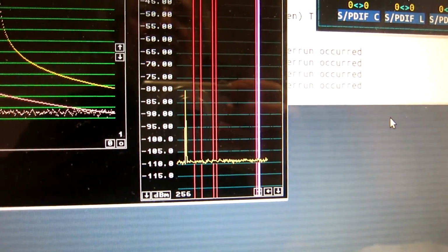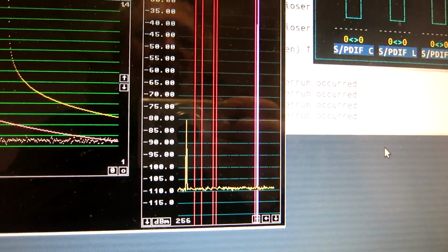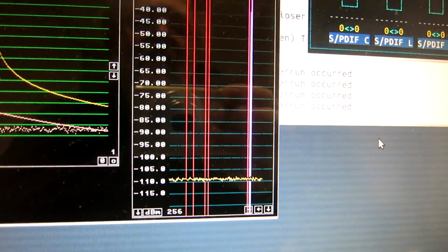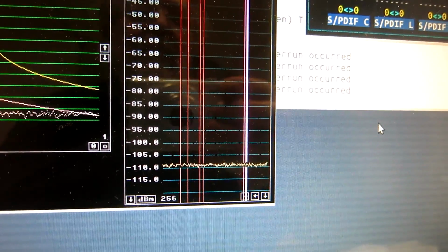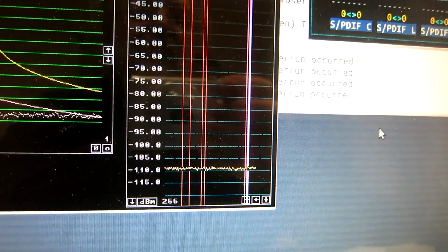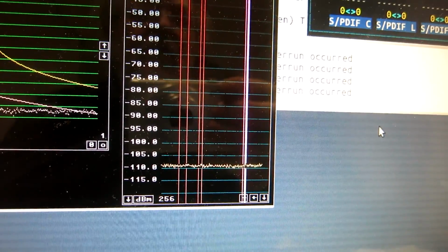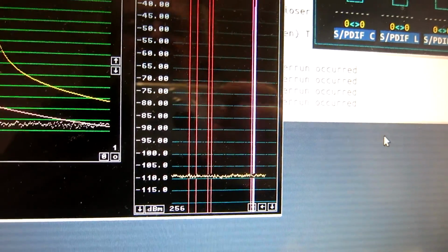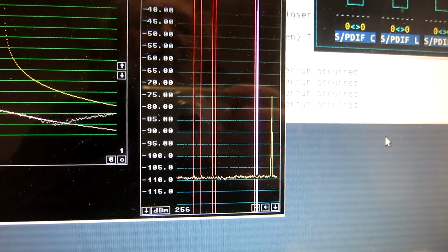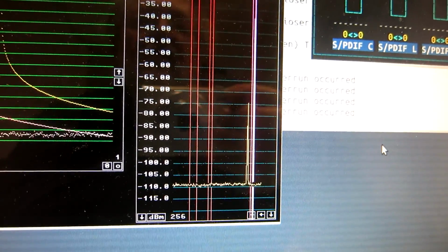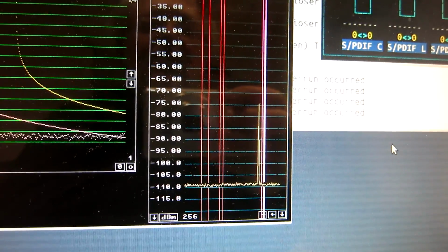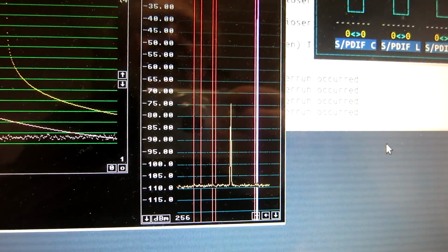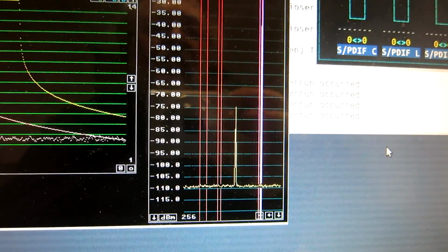And as it happens, the Windows driver seems to be a little bit better, because when evaluating dynamic range, it became a little bit bigger. That was dynamic range without any strong signal. But as you can see now, the presence of the strong signal does not affect the noise floor. So this is always the problem with hardware, how to get the correct drive routine.